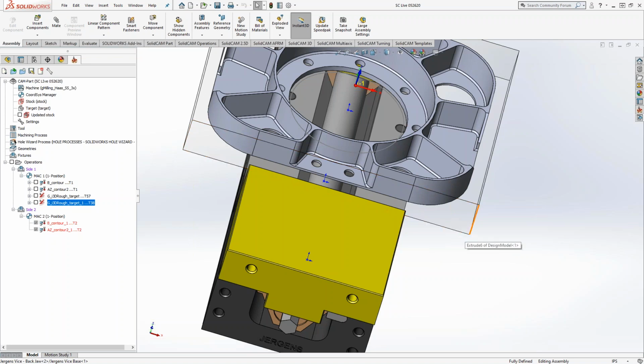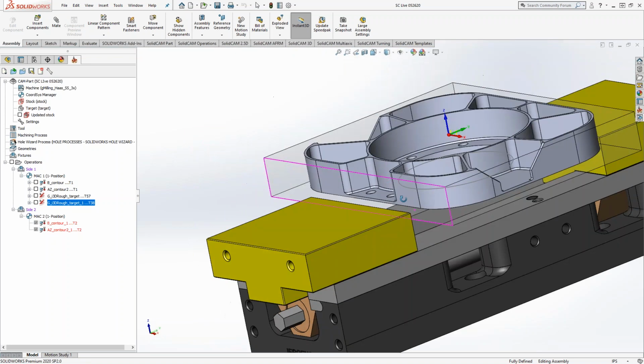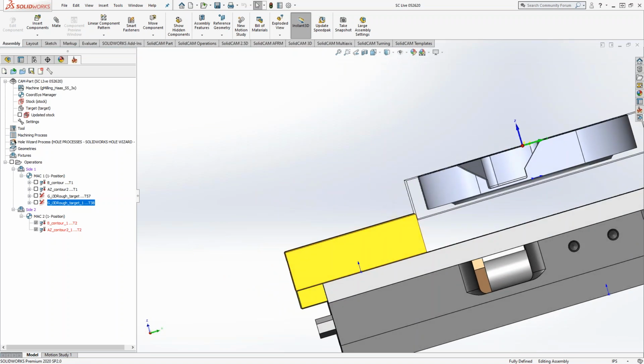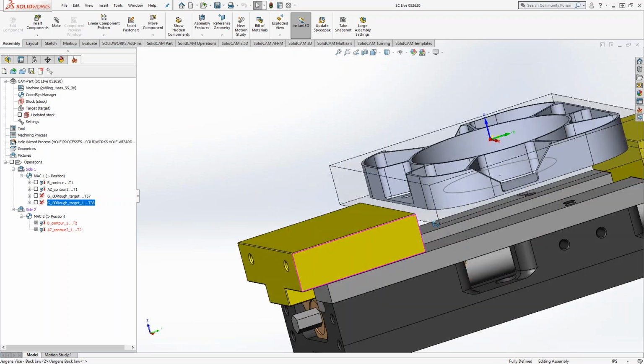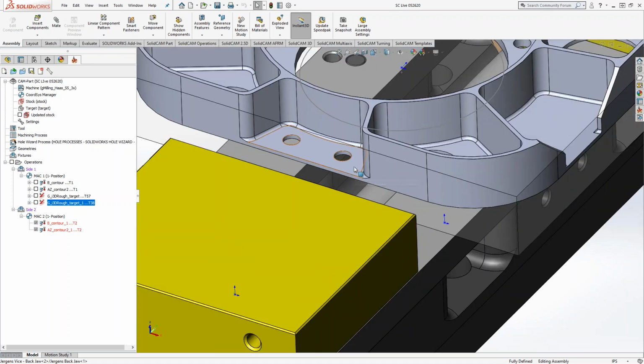But basically, exactly like Kevin said, there really is no need in my case, the way I set up this part, for tool 38 to go past that level right there. So I probably could have just said, go as far as maybe the bottom of the pocket, and then that's it. So that functionality also exists. But that also highlights the fact that you can set individual levels per tool as well.